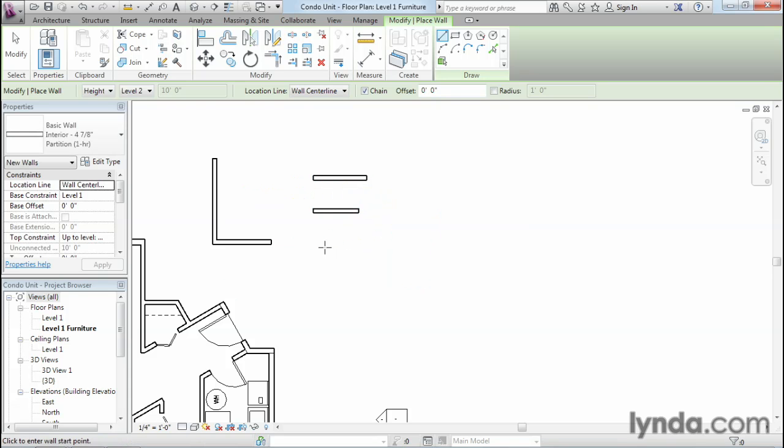Let's press escape again. Now, when you want to do just inches, you can either do the inch symbol to make it clear to Revit that this time you mean 10 inches, not 10 feet, or using that same method I just showed you a moment ago, you could do 0 space 6, for example. And now I've got a wall that's exactly 6 inches long. So you can do all the same things we can do in AutoCAD. It's just slightly different, so you're just going to have to get used to what some of those differences are.